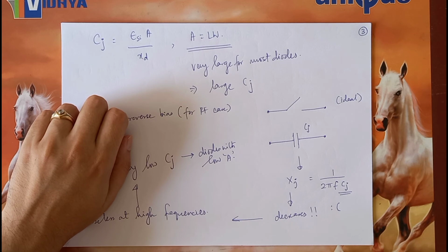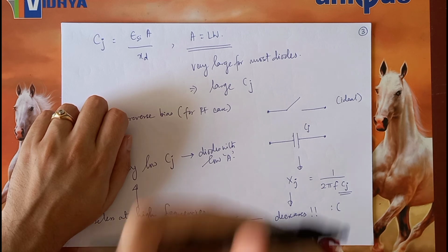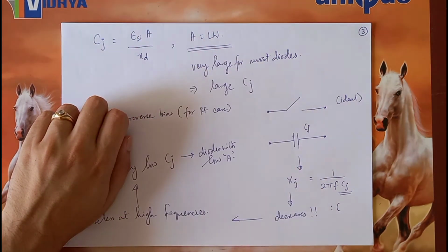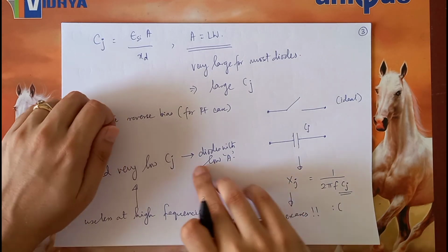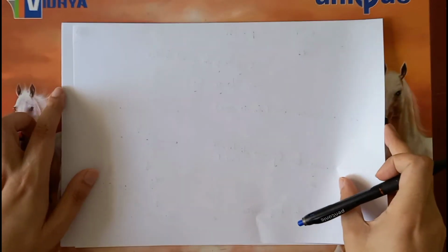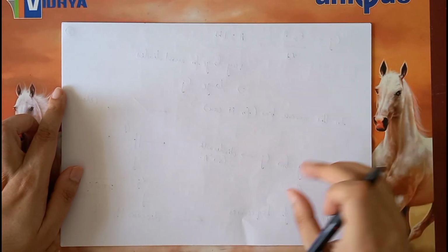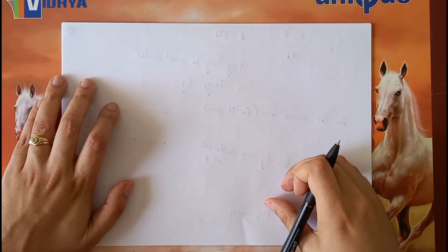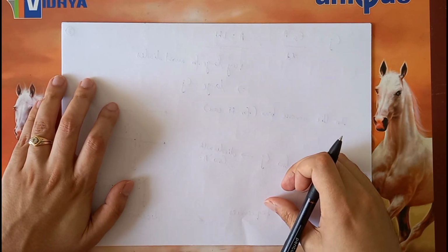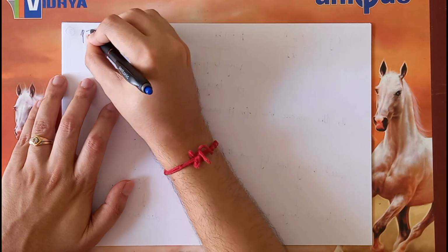Well, in that case, a very small modification can be done to the PN junction, where without having any strong reverse bias, we can still obtain a very, very low capacitance. And thereby, I introduce the very first type of specialized RF diode, and that is called a pin diode.